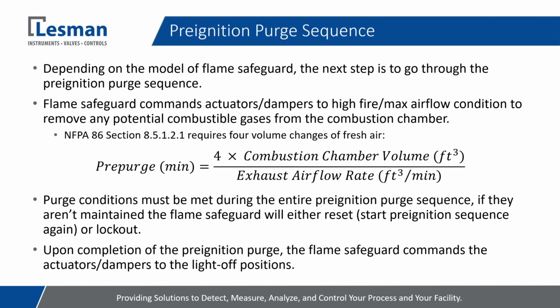Now, again, not every flame safeguard has this behavior. Some versions of the 7800 series flame safeguard and FireEye and other flame safeguards do their pre-ignition purge prior to going through the initiate and safe start check.